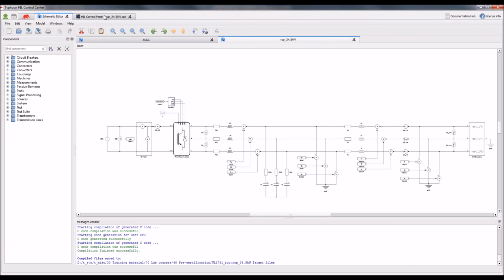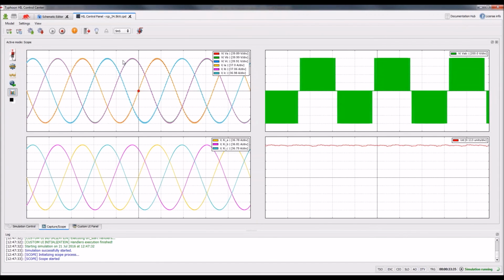So once we compile this, we can just check whether this schematic is working. Just briefly, double check the time domain signals. Okay, it's pretty straightforward. We are seeing that we are modulating, injecting the power in. Voltages are fine, currents are fine, so everything is good, meaning our model is actually ready and prepared for test suite. So at this point, we are okay.